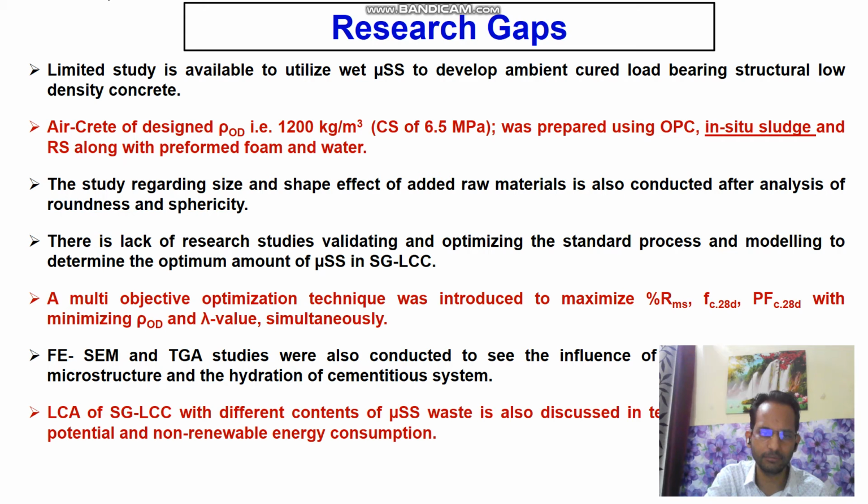For the microstructural study, thermogravimetric analysis was also conducted to see the influence of microfine sludge on the SGLCC microstructure and hydration of cementitious phases. Life cycle assessment, along with cost and natural resource conservation analysis, was also calculated in terms of global warming potential and non-renewable energy consumption.